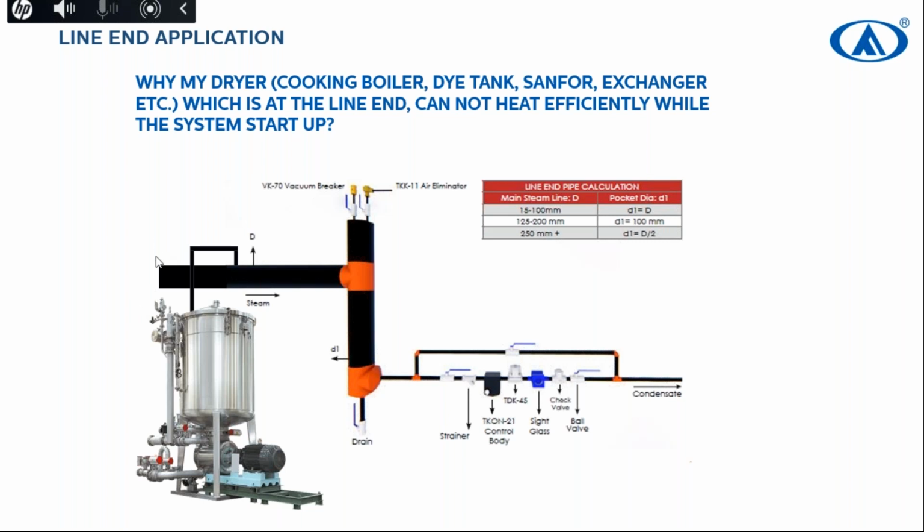And when you close the system, the 6 bar steam in the pipe turns suddenly into atmospheric condensate. And all this condensate will make some blanks inside the pipe, and all these blanks must fill with something. With what? With air, because there will be vacuum. And if you don't use a vacuum breaker, it will take all the air from the gaskets between two flanges.